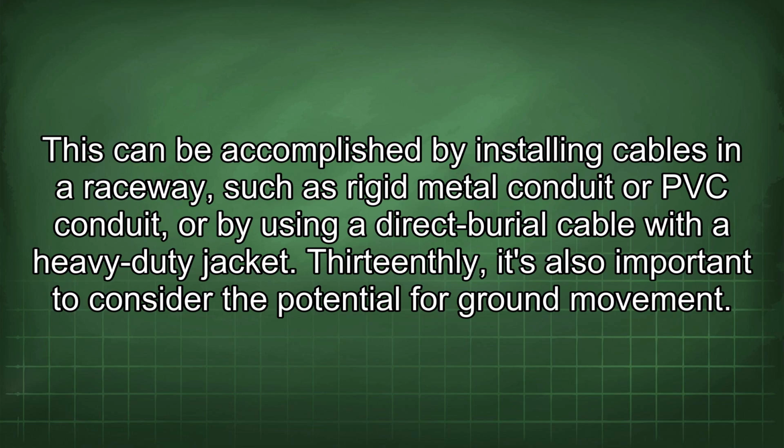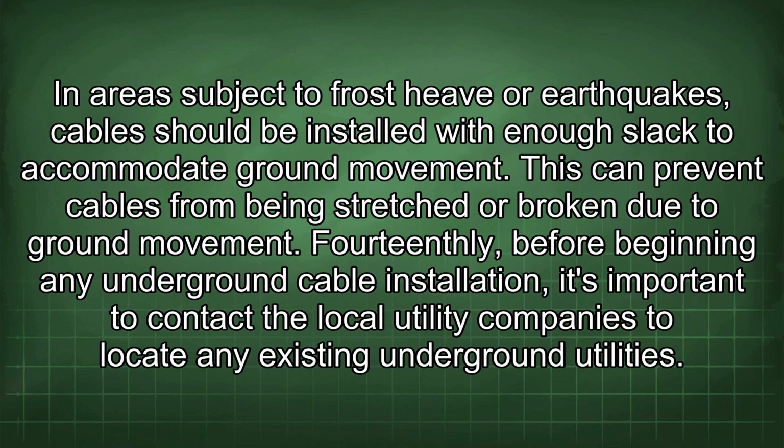Thirteenth, it's also important to consider the potential for ground movement. In areas subject to frost heave or earthquakes, cables should be installed with enough slack to accommodate ground movement. This can prevent cables from being stretched or broken due to ground movement.